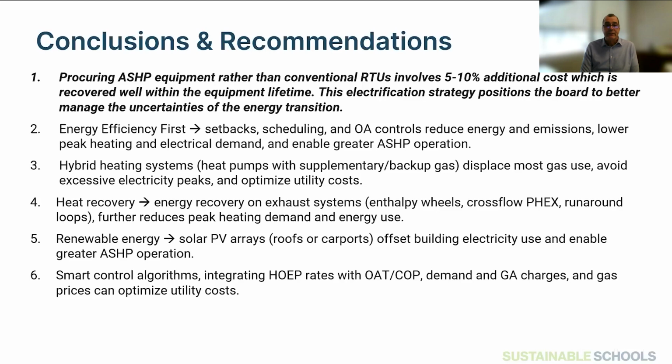VRF technology is probably where we're a little bit more on the fence. We have introduced VRF now in several schools, and we're continuing to convert some of our older style of heat pump schools to VRF. But we are seeing significant cost to that. So we may pause on that, especially with the changes in refrigerant and how that might change that whole sector. We may pause on installing further VRF units until we have a better understanding of where we're going in terms of whether they are cost effective and how much more or less cost effective it might get as refrigerant rules change in Canada.